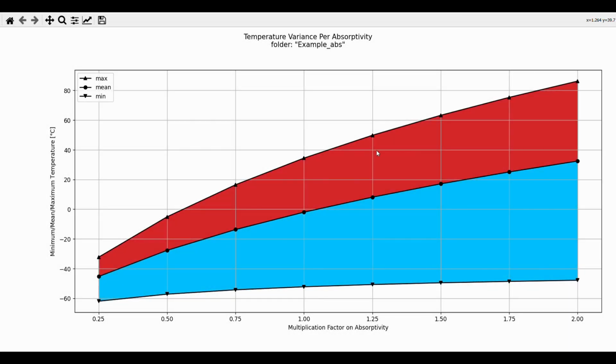So, well, I already showed you all these plots before, but I previously showed you for the day in the year. And in that case, on the x-axis, it was the actual value of the parameter. So it was the day in the year, 1, 50, 100, 150, etc. But in this case, because like I explained before, for a lot of parameters such as absorptivity, emissivity, heat capacity, all those parameters, it's a multiplication factor. So in that case, it will mention it here on the x-axis, and your 1.0 will be your baseline. That's just the normal model by itself. And then as you apply this multiplication factor to your input parameter, that's how it changes. So just make sure to read this X label properly and realize that these are not actual values, but multiplication factors in this case.